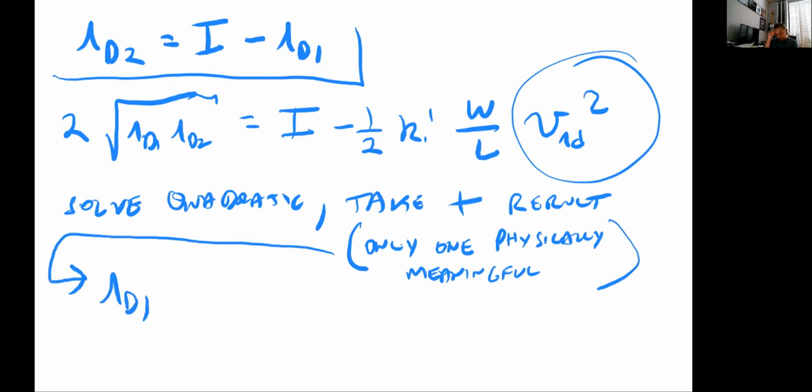the drain current in transistor 1 in this case is going to be greater than half of the bias current. So we are putting a positive differential voltage in.